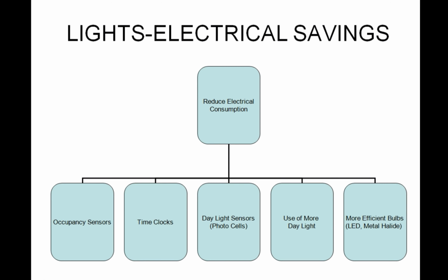Okay, the way we're building our buildings, we're using a lot more windows and facades, so that we can get more daylight into the building. And on top of that, not only are we using windows, but we're eliminating the exterior offices that used to go around the perimeter of the building and allowing more workspaces on those exteriors so people can use the daylight and reduce the amount of artificial light we need to generate using electricity to work in those areas. And that's part of the LEED requirement. Okay, what percentage of your building has what they call natural light or access to natural light. Basically, can you see out a window from where you work?